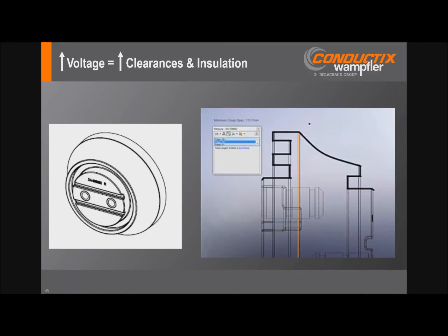So voltages are typically 600, 750 volt DC or 480 volt AC, and of course, those are the primary drivers for insulation design. Environmental conditions like UV exposure, moisture, pollution levels also have a significant impact on the effectiveness of those insulating materials and should be considered in system design. Insulators must be designed with the necessary geometry and materials to meet system requirements.